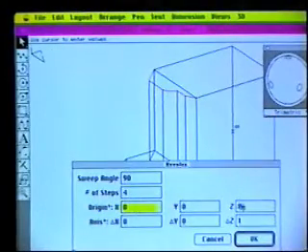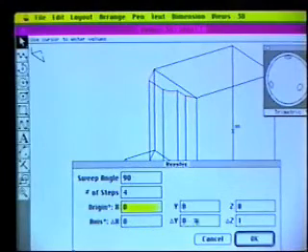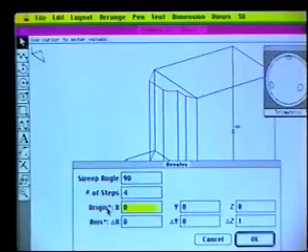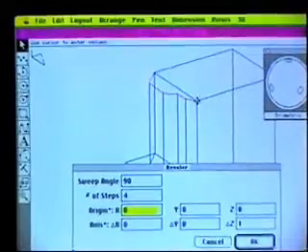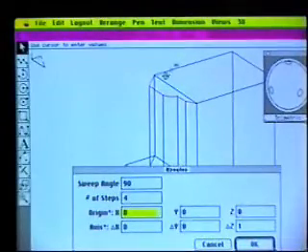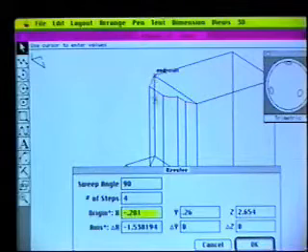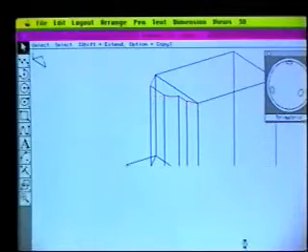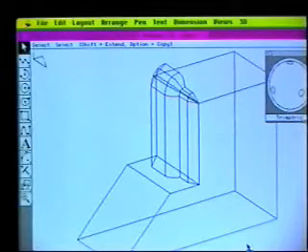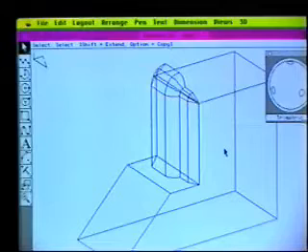But these 6 boxes, I really don't have any idea what numbers I need to put in there, but I don't need to, again, because of this asterisk. So what I can do is go in with my cursor and just define the axis of revolution by saying that it is from here to there. And notice these numbers, there's no way I could have filled those in correctly like that. And then I say OK, and there it is. So my revolve happens automatically also.